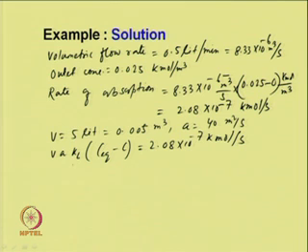From where if we substitute a, V, and the equilibrium concentration is given and C is known to us, C is 0.025 and this is 0.034. So, substituting these values we can calculate K_L is equal to 1.15 into 10 to the power minus 4 meter per second.